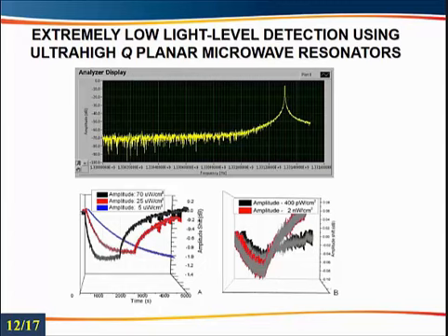So the way it works is interesting. When you have carriers incident on the titanium nanotube arrays, obviously the conductivity increases because electron and hole pairs are generated that participate in conduction. But because there are so many traps because of the high surface area, the filling of the deep traps by light increases the number of bound charges in the dielectric and increases the capacitance. So there's both a change in the capacitance and the conductivity, and microwave resonators are an excellent way to sense that.